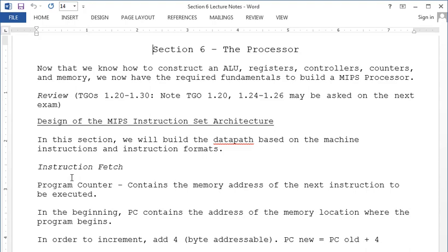After you see the data path, the term for it will make a lot more sense. It's called write back. Because we're going to be going instruction memory, decode, registers, put that information in the ALU, then we check the data memory, and we're going to use a multiplexer, and it's going to go back to the registers. So it's going to be write back. Instruction fetch, instruction decode, execute, memory, and write back.